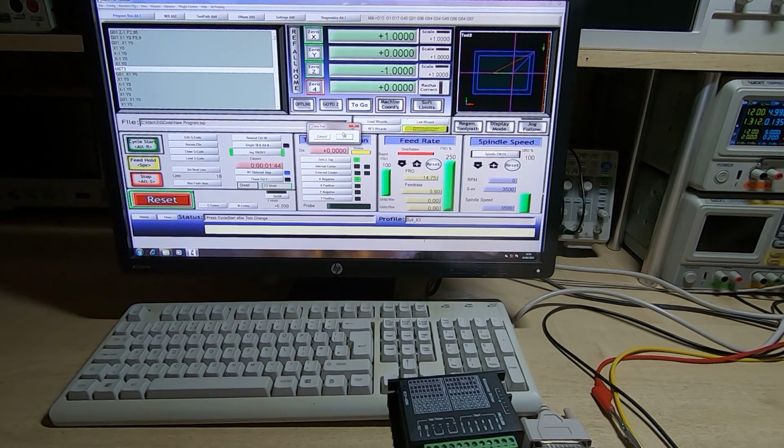So the way I've set up my machine, I've written a couple of macros, and one of the first things it does within the first macro is it throws up this selection box. If I just click cancel, it is the same as the macro not being there, it does nothing. In fact, it's the same as the original macro that comes with MACH3. So I will click on cancel. Notice it's gone through, the tool change light is flashing, and we'll do what we would normally do, click on start, and it continues. So I'll stop this operation and we'll go back to 0, we'll rewind.